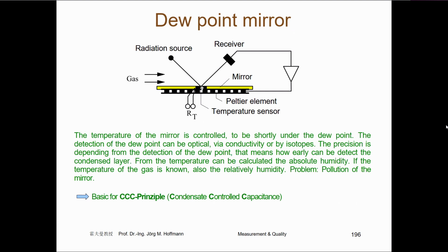And then the question every time is, how much do I have to dry the gas so that you get no water inside of the tubes, because over time that would destroy the tubes by rust. So you have to dry this gas at first. But the drying process needs a lot of energy, and therefore it should be dried only as much as necessary.